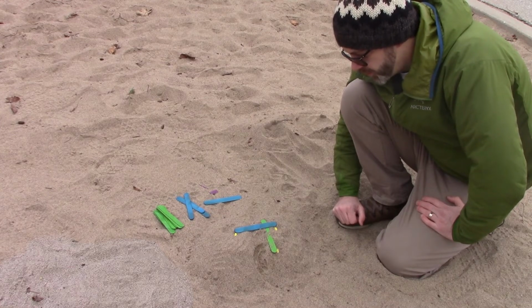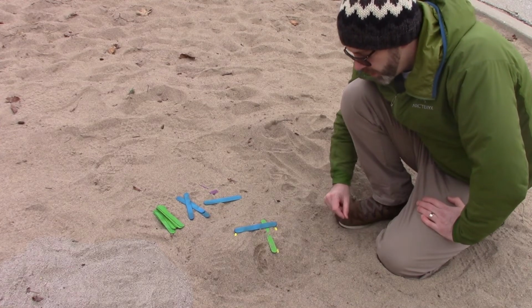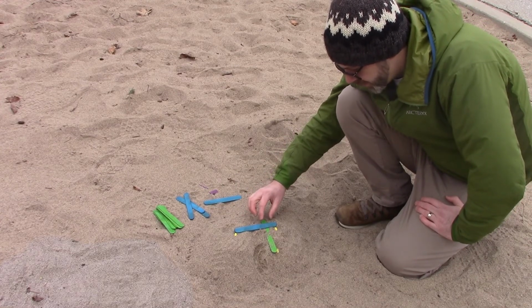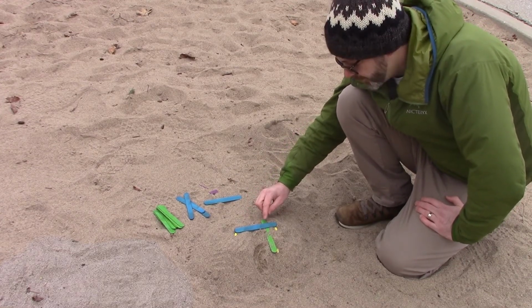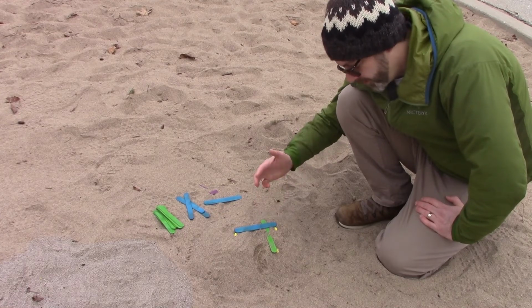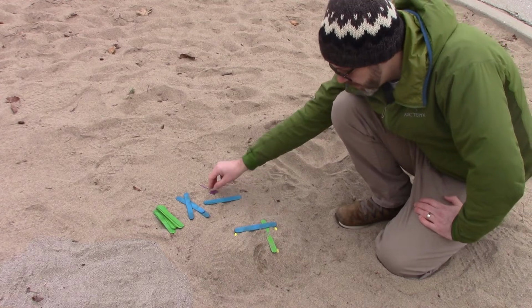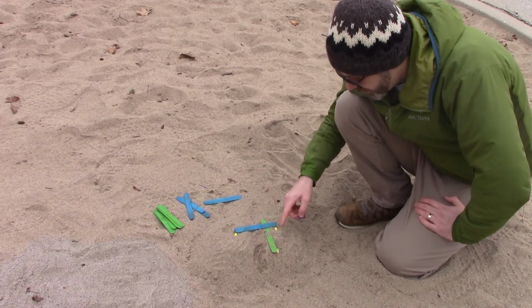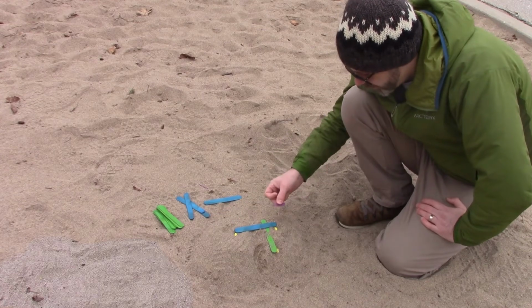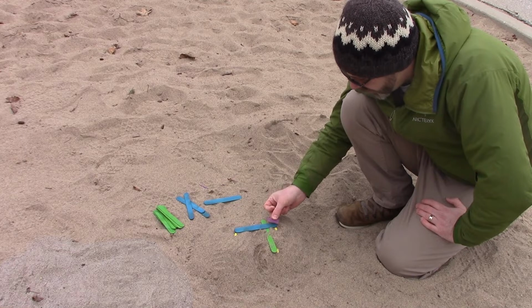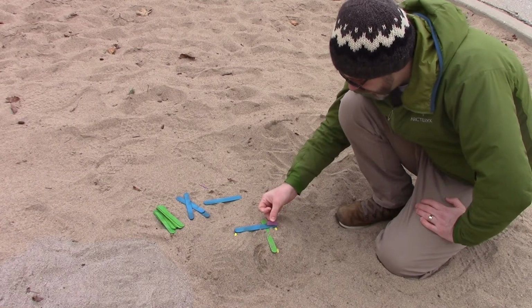And in order to do that, we need to determine the perpendicular distance from this green line, our first structure contour line, or the strike line, down to one of our other points in space. So we could do it up to that one or this one. This one's closer. And in the example, I use a purple line, so we can calculate that perpendicular distance.